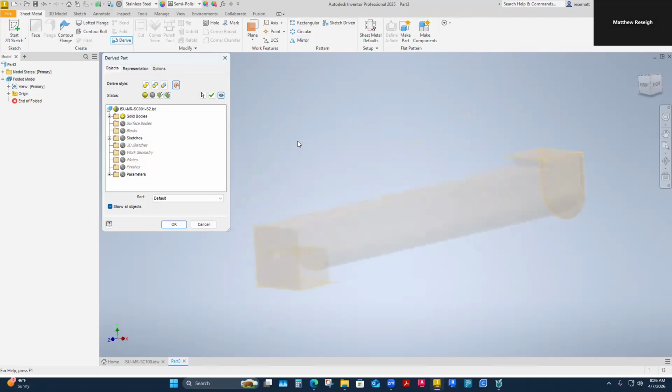Well, I'm going to do one more thing here because I don't think we've toggled through these very much, but I did tell you have access to everything that you've created that solid with. And one thing that I'm going to need, because what this part is going to make are the end plates here. And we designed the end plates in the solid to be ready to have some flanges put on them. It's why they're built the way they are. I'm ready to use the flange function.